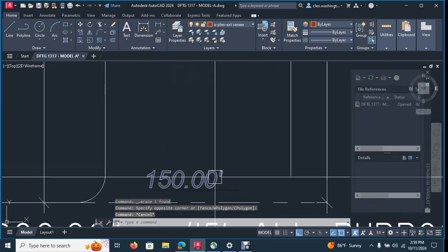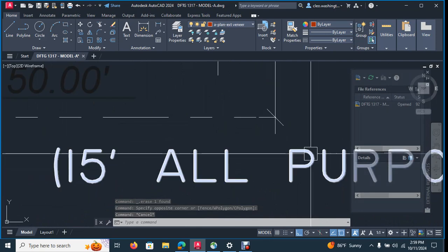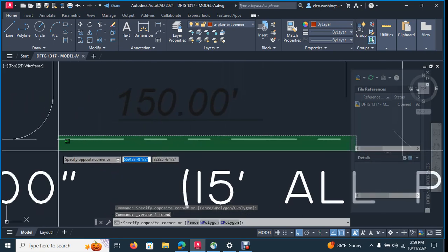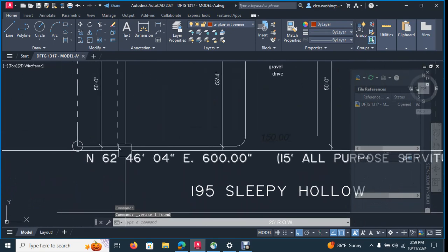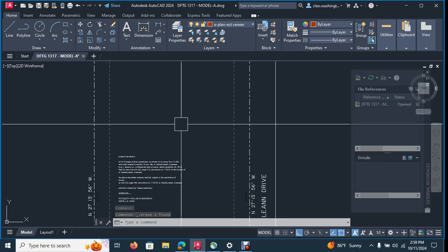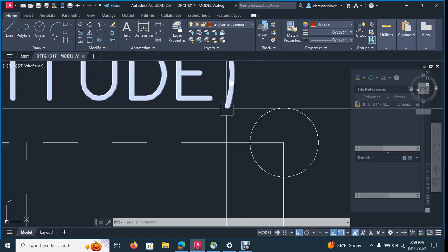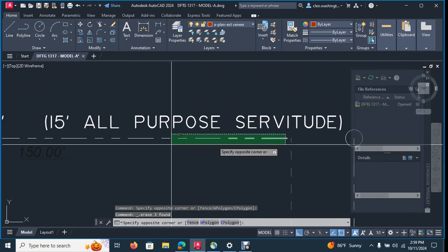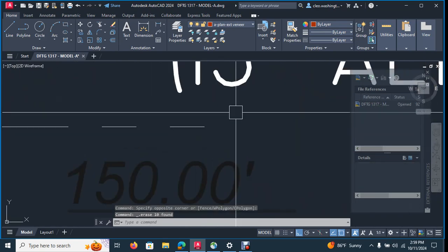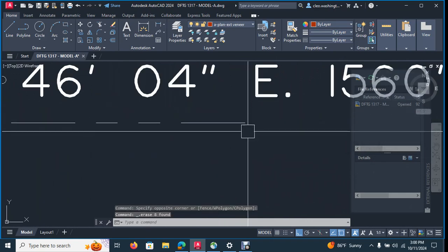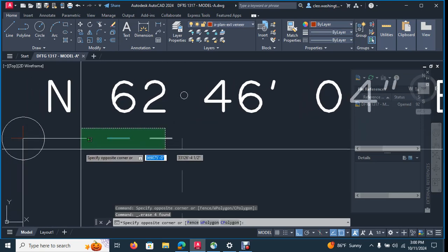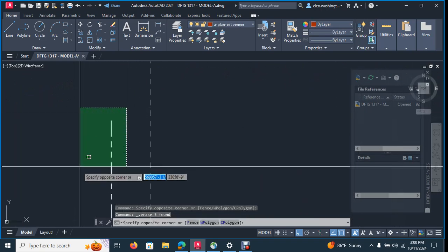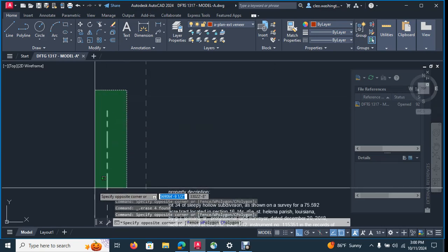Leave that one there, but let's delete the property lines. Leave the dimensions because I want to show where we need to dimension our building. We'll leave those for right now. So let's take these out, take that out. I know I deleted the one that was on the property line layer. We're just going to redraw it.